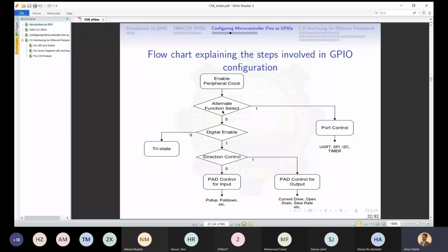Among those alternate functionalities, different peripheral devices are multiplexed to that particular pin via some hardware. There was a special register called the port control register. That port control register was selecting one of those peripheral devices to be multiplexed to that pin, and that pin will start behaving as that peripheral's transmitter or receiver.